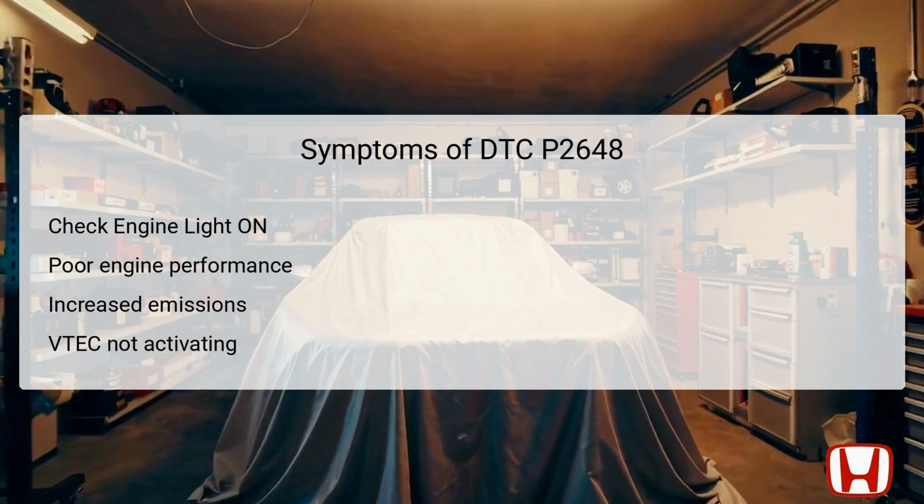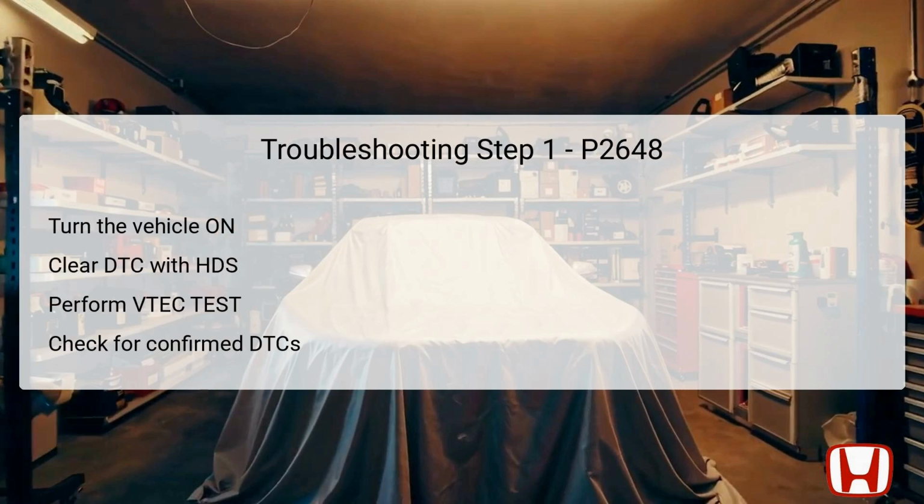The first troubleshooting step for addressing DTC P2648 involves verifying the presence of the trouble code through the Honda Diagnostic System (HDS). Start by turning the vehicle to the on mode without starting the engine. This prepares the vehicle for diagnostic testing.